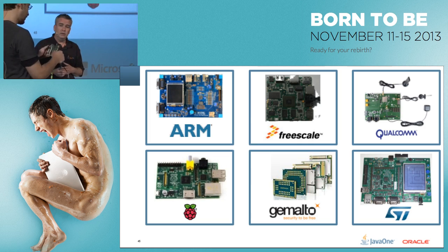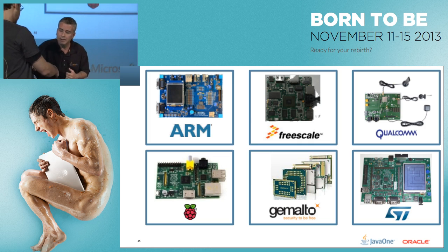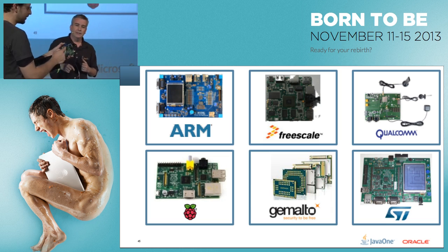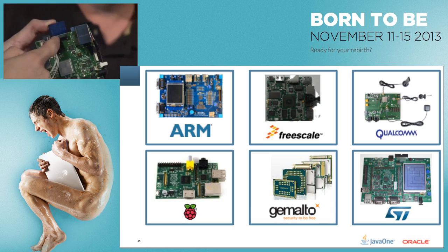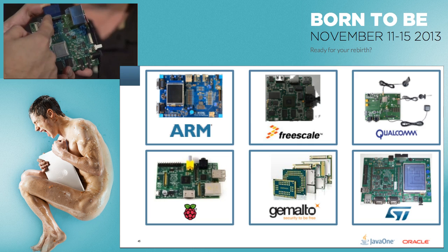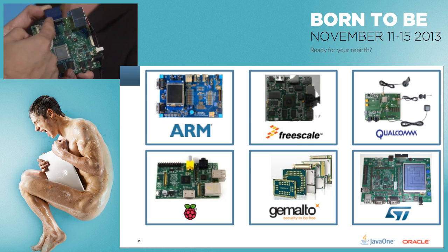I found the SATA controller. It's this one right here, right? This guy, the port. No. No? That's the power for the SATA. Oh, where's the SATA? SATA's right here. Okay, so Gary's corrected me. There's SATA power, the white one over here, and then the black one over here is the actual connector for the hard disk. Yep. That's pretty cool.